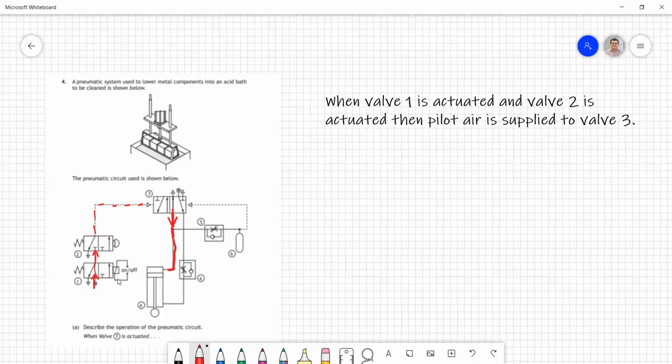We're going to come down this way, come in the top end of our piston here, and of course we know what happens when we supply air at this end of the piston, it's going to cause the piston to outstroke. So our piston will now move to this position out here. Our piston will outstroke. Once the piston is fully outstroked, though, that's when there'll be no further capacity for air to travel down the way.